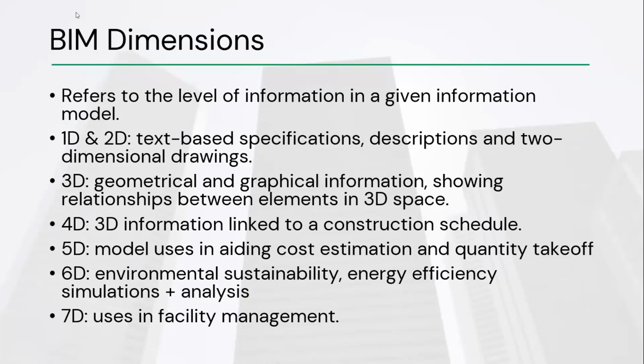So if you look at the traditional takeoff where you are using blueprints and measuring rulers, I think that takes a lot of time. But then the automation of being able to measure from PDF drawings adds an improvement on that process. But also, if you look at the capabilities that BIM offers, if the designers and the model authors are able to accurately model and create all elements, components and objects, and the schedules are correct, you can extract those schedules from the 3D model and use that for cost estimating.